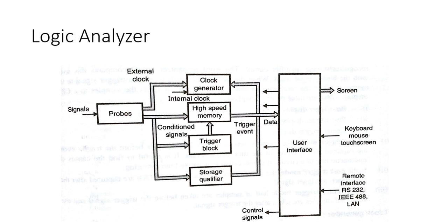What is the use of probes? I have discussed earlier that they are used to take the signals from the circuit. There are different logic families available, like TTL, CMOS and NMOS, and based upon this the design will be different. Another important use of the logic analyzer is to identify malfunctioning of the system. Suppose there is a system which is not working properly, and you want to debug that system, then you can use this logic analyzer.